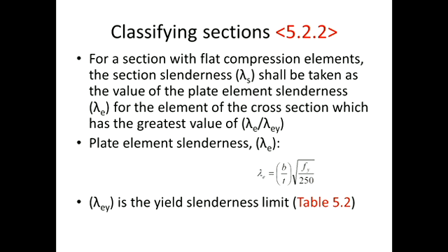To determine the section slenderness, we have to look at the elements within the section and look at the greatest value of lambda e over lambda ey.